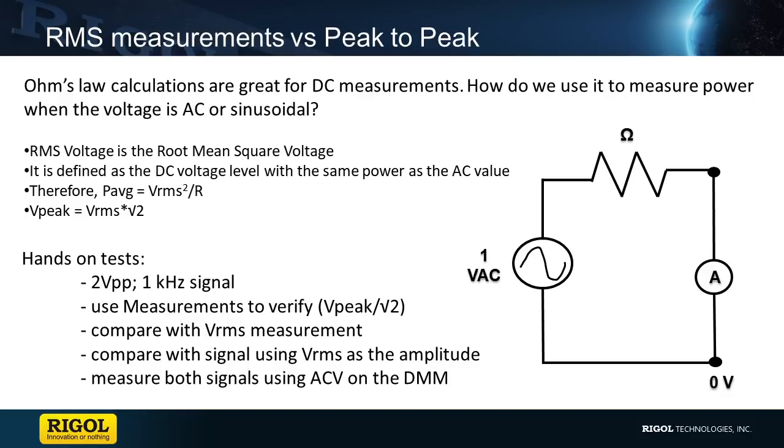So it's a great notation for calculating power, as well as normalizing those AC signals. Depending on the offset and the amplitude, there's a lot of different power that is actually developed. But volts RMS gives you the notation that tells you, hey, that's the equivalent DC value.